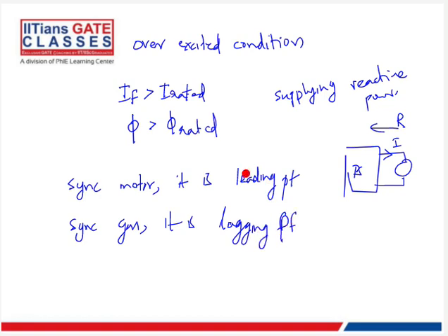Here it is supplying leading PF, here it is supplying lagging PF, right? The current and the reactive power must be in the same direction, so it is lagging.